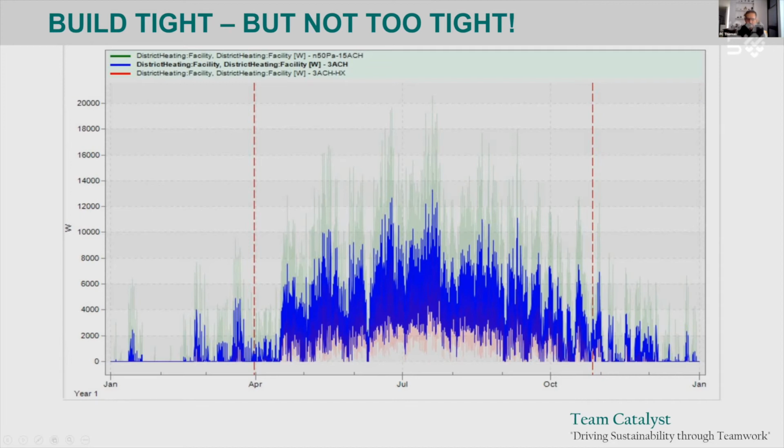Step number two is you go, well, once you've tightened the house, there are some unexpected consequences. Okay, you have moisture in the house. In a leaky house, the moisture disappears because it leaks. But in a tight house, the moisture stays there, and you might start to build up mold. Okay. In a leaky house, you don't worry about carbon dioxide concentrations. In a tight house, particularly in a bedroom at night when you close the door and go to sleep, the CO2 concentrations inside that room will start to increase.